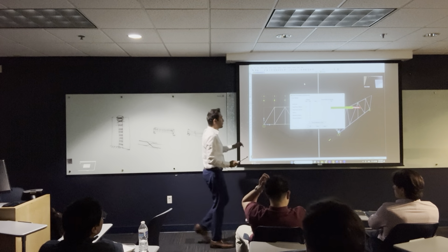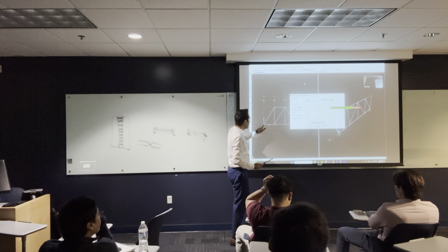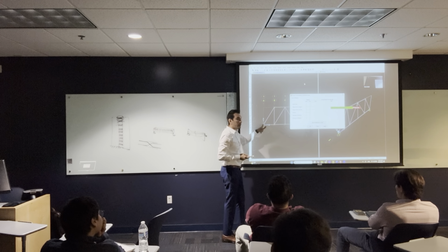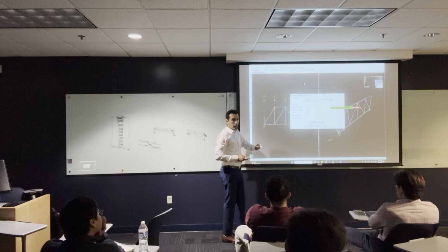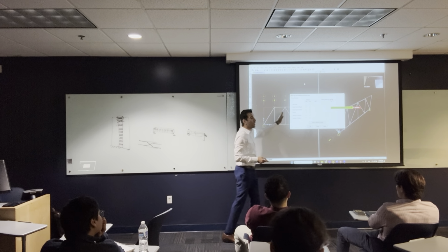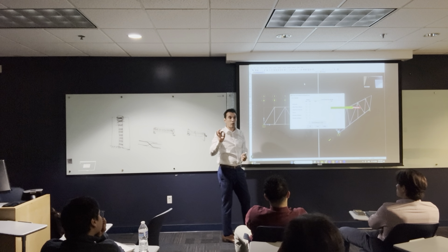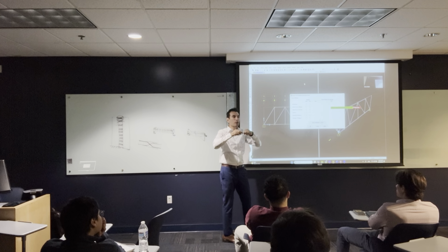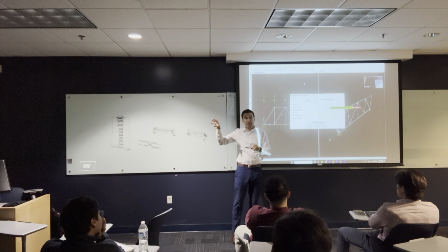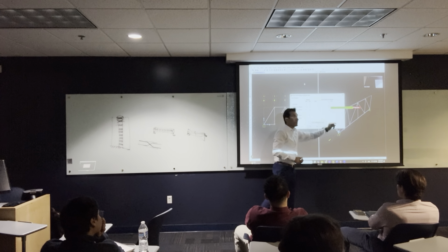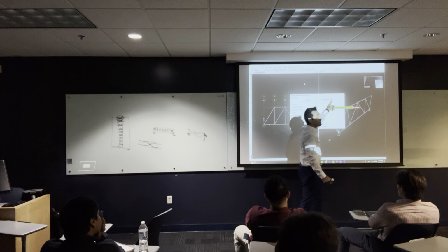Basically, we can tell SAP 2000, hey, I wanna release all the moment here. I wanna make the stiffness of this joint equal to 0. Okay, so we can do this for every joint. However, let's say that you have a spring and you don't want this joint to have 0 moment. There's a little bit of rigidity. You have to calculate the stiffness of the spring and you can find the value of the partial fixity. See, frame partial fixity spring.